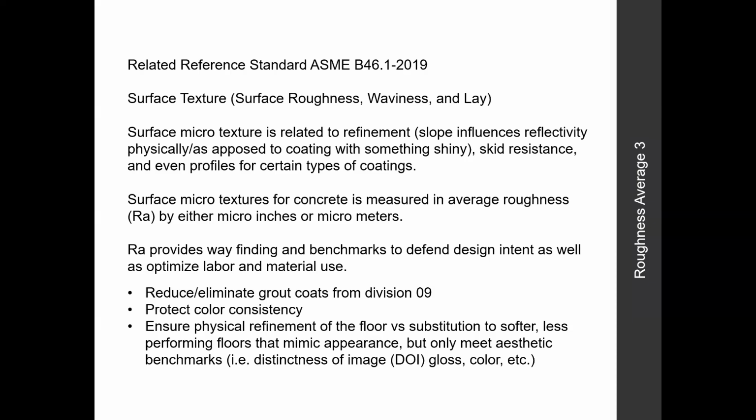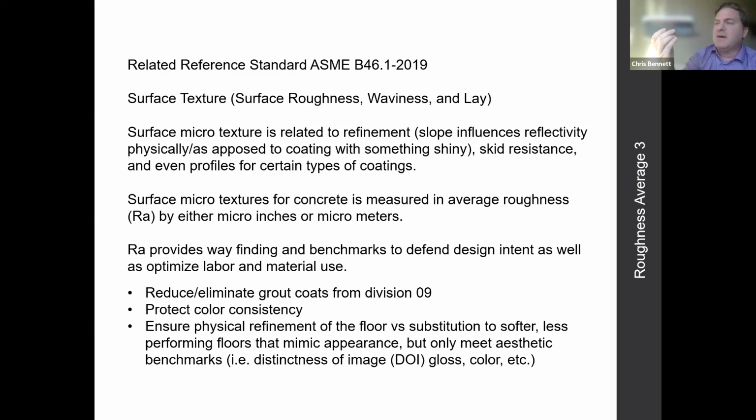One of the things that we noticed right away with the training, after we exposed aggregate, the polishing contractor came in, and the first time around did not have a profilometer device, an RA device. And I'm going to turn on my camera here real quick rather than go back a slide, just so everybody can kind of see that there. This is a profilometer, and there's a little metal stylus here. And that stylus goes over the peaks and valleys, all the nooks and crannies of that surface microtexture, and will give you a numeric reading.